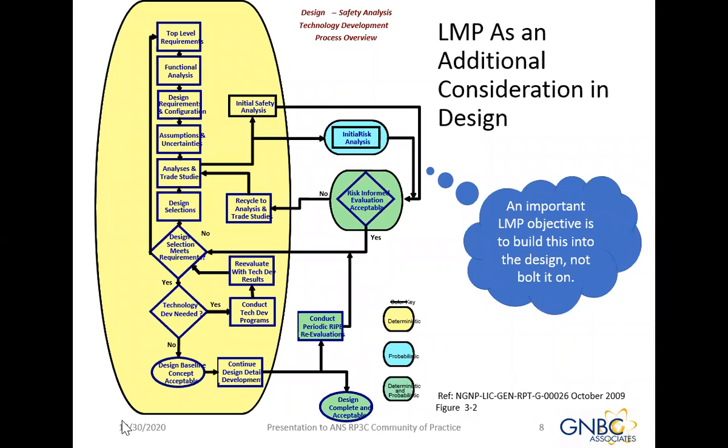With the top level requirements developed, there's a series of other activities that takes place in any traditional design process. This is completed principally in the pre-conceptual, conceptual, and preliminary design phases, as shown in the yellow spaces. With the addition of modern risk processes, the additional capability to examine the design using PRA tools brings insights on the safety performance of the integrated plant and clarifies risks and safety significant features that should be modified, added to, or considered for special treatment in the process of design completion.